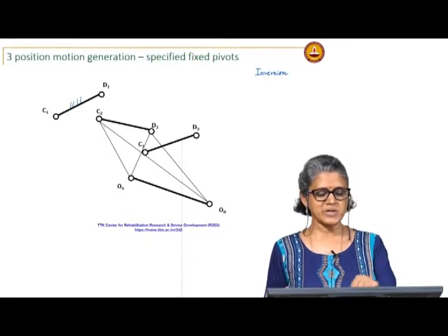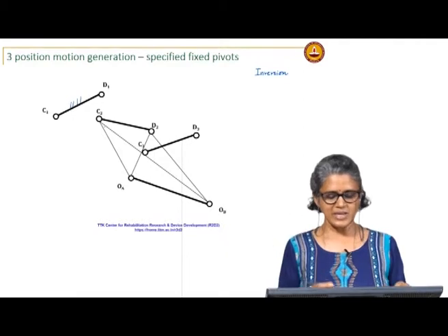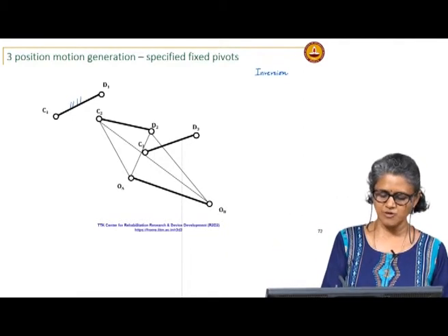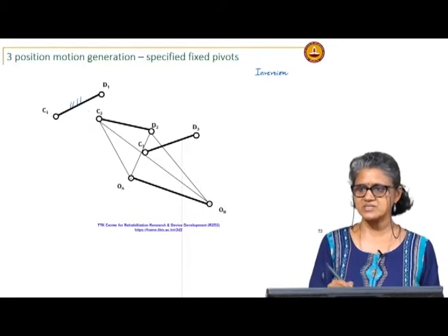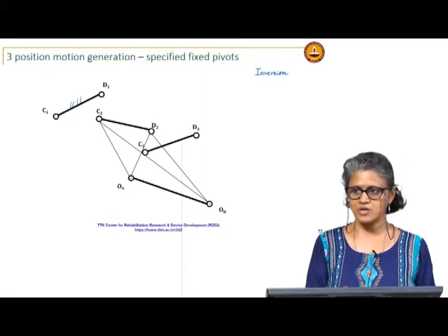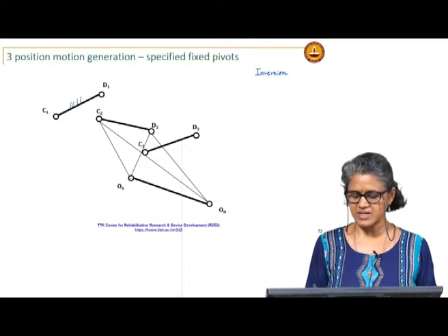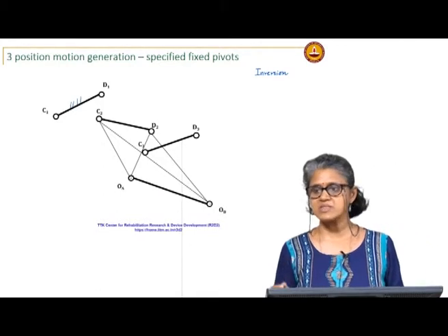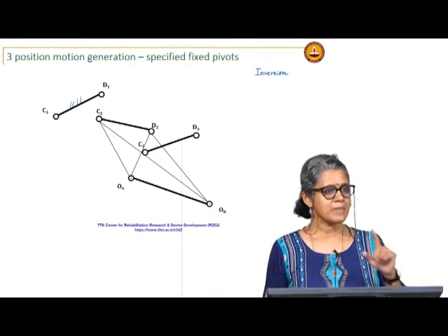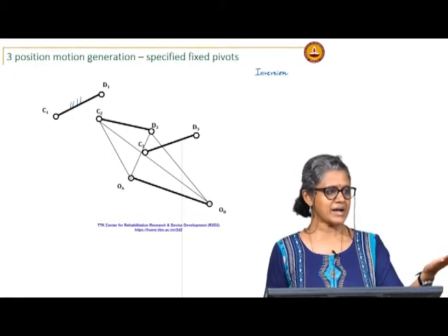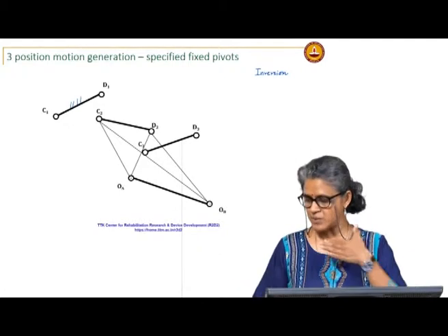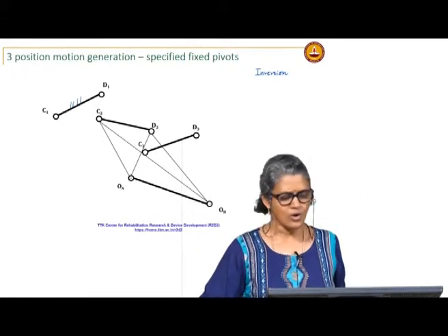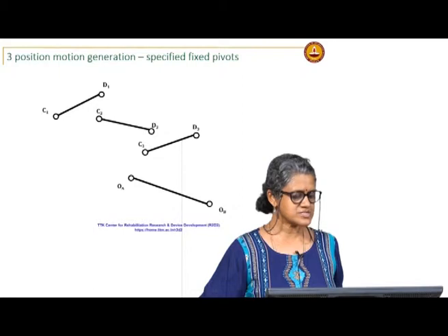With respect to C2 D2, I can find the location of OA and OB like this. I measure the distances, so I can locate OA with this triangle and OB with this triangle. Now I transfer that, because I am not moving, I am on C1 D1, onto that first position.